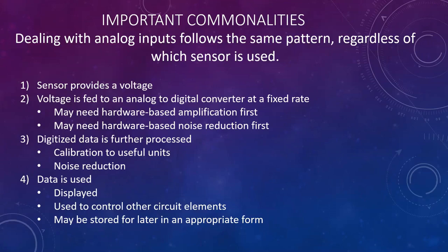But sometimes you know a signal is going to contain some sort of noise, and with a couple of electrical components, you can just pass the signal that you're getting from your sensor through a capacitor and a resistor, and then what ends up being detected by your analog to digital converter is now noise-free because those components have already smoothed out some of that stuff. We won't be building those circuits, and those are actually fairly specific to individual devices anyways. So what you're getting today is going to be much more general purpose.